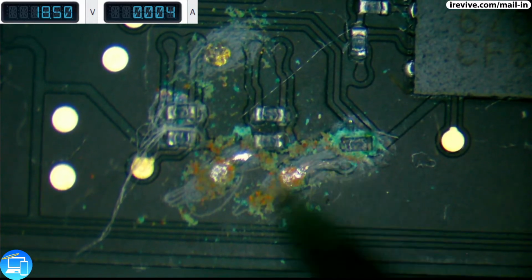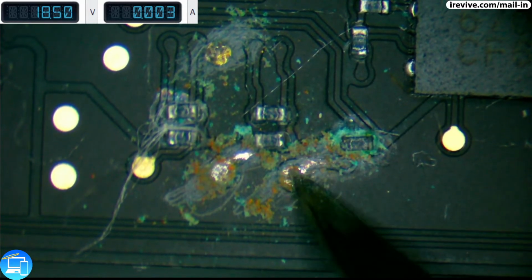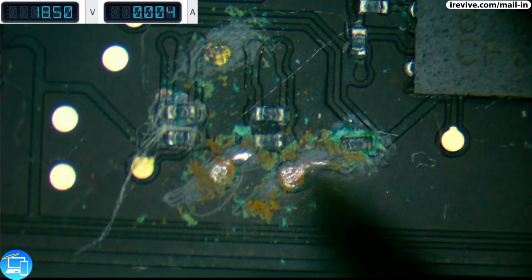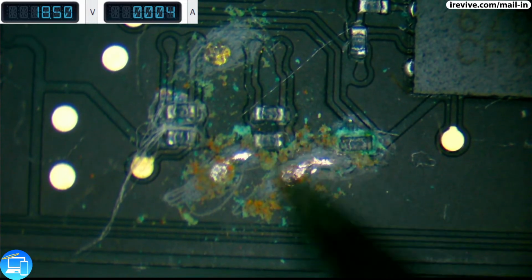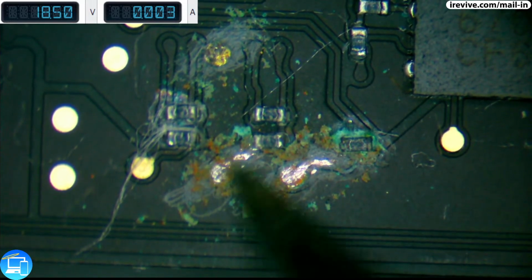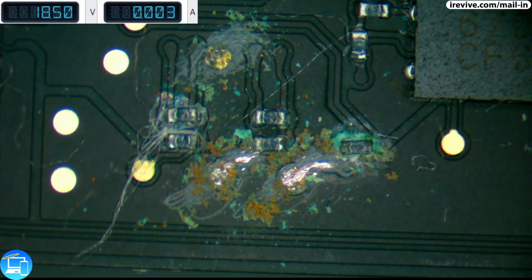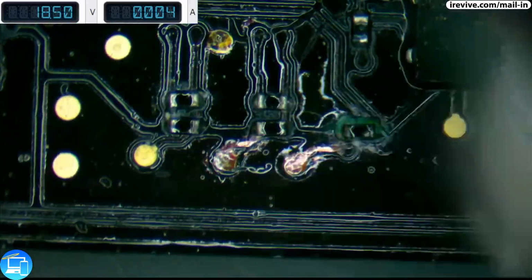And some people will just go ahead and remove these components with the corrosion on. That's fine. Just me personally, I like to go ahead and get a clean canvas to work with before I start soldering. That and flux and rust and corrosion just makes this really thick molasses-like residue, and it makes it a little harder to solder with. So now I'm just going to clean up the area a little bit more with some Windex. Sorry, not Windex. I'm using isopropyl alcohol here.